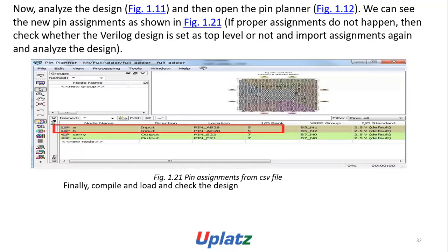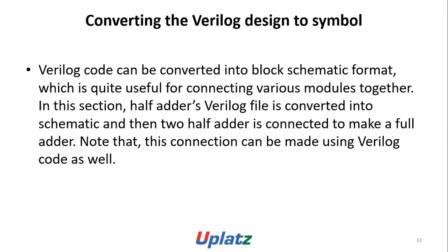If the proper assignment does not happen, then check whether the Verilog design is set as top level or not, and import assignments again and analyze the design. Finally, compile, load and check the design.